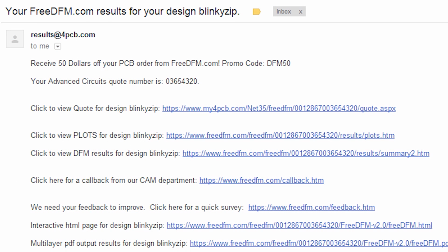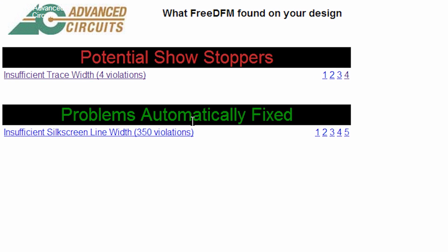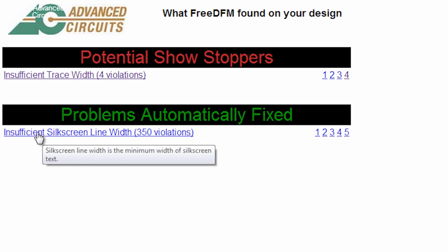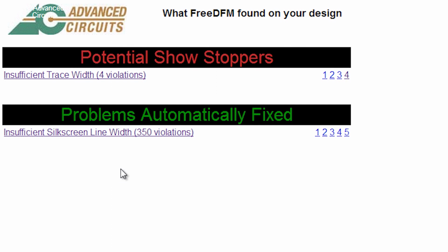By this point, you should have gotten back your design check from free DFM. Again, this is just one of many DFM check services. But you can click here to view the DFM results for the files we uploaded. And now we can see that there's some showstoppers and things that were automatically fixed. So the things they automatically fixed are insufficient silk screen line widths. That's really not an issue. It means some places we made the silk screen pretty thin and they want it to be thicker to print it. They'll be able to automatically fix that when they fab the board.